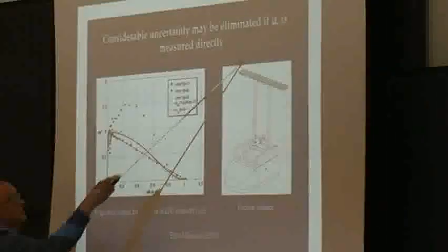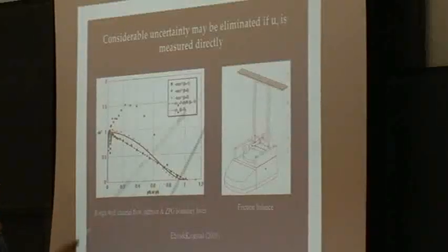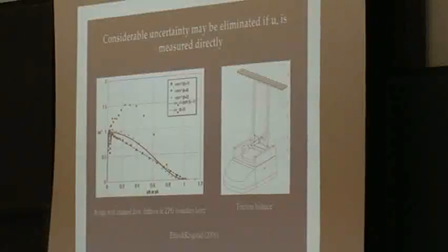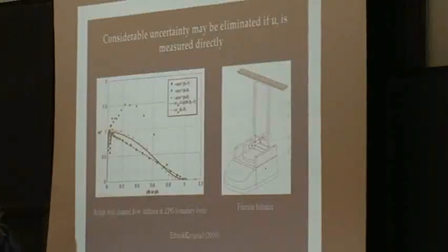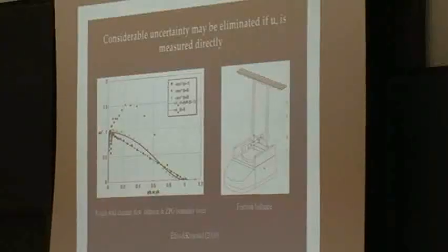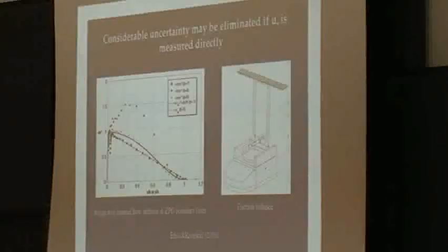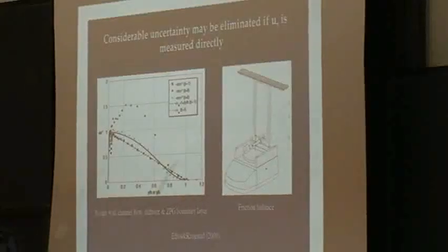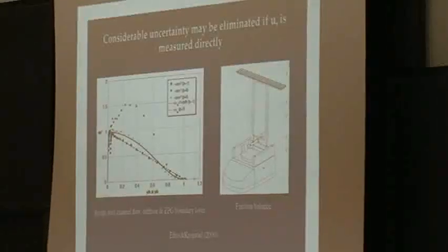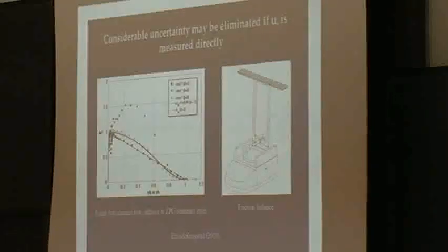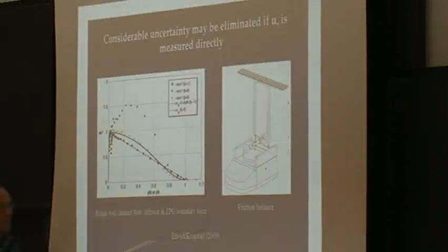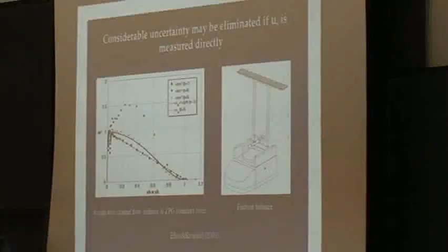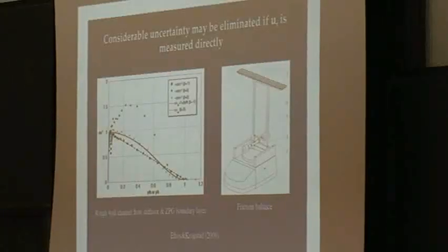Here's our test surface. It's a section of our wind tunnel floor. Under that, we have put a force measurement device, which is really simple. You go in the shop and you buy a small balance. You can buy it to weigh your post or other small quantities. We have a balance here which has a resolution of 1 milligram.